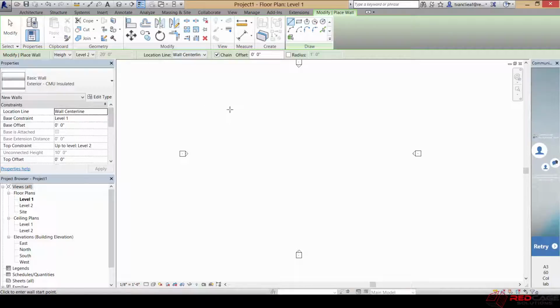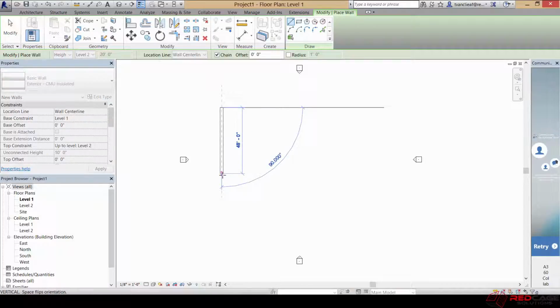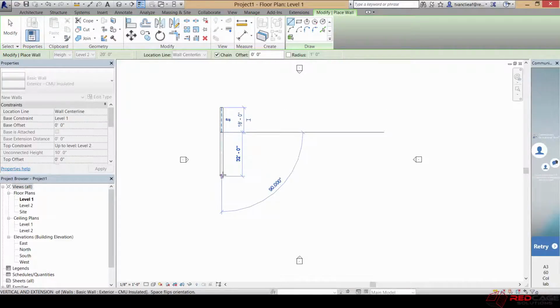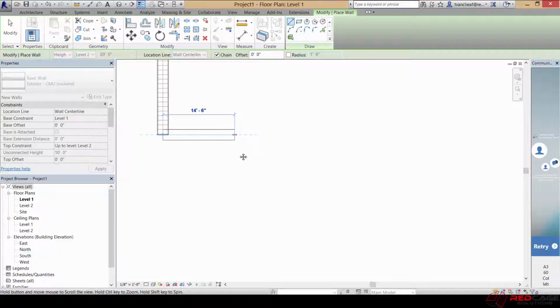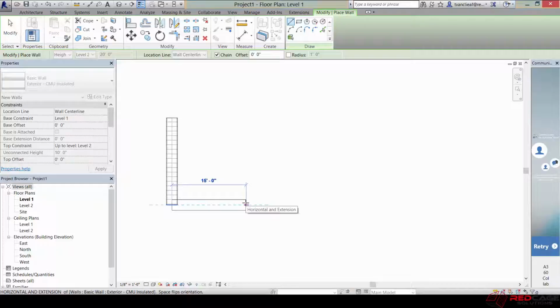So you'll notice that I'm in a pretty simple, straightforward drawing environment, and when I start drawing, just by clicking that left mouse button, I'm already getting some dynamic input options here. If I wanted to, I could type in 18 here, and I get an 18-foot wall. I didn't have to type in any units. I just started getting what I wanted. If I type in 12 here now, and I want this to be, say, 12'6", then I'll type in a comma and a 6 after, and I'm going to get my 12'6" wall.